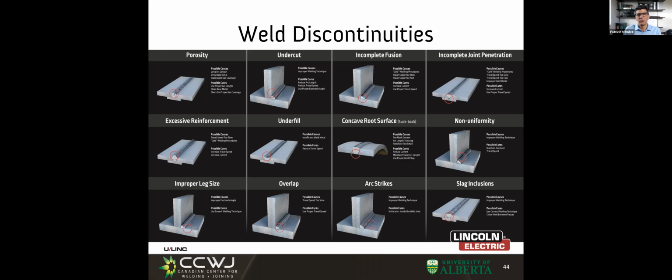If I'm doing a nuclear power station and I find a porosity, likely I will need to remove it. And then the same porosity that before was nothing, now it becomes a defect that needs to be fixed. So it's an important concept, a subtlety: the fact that it is imperfect doesn't mean it's a defect. Very important concept in welding.